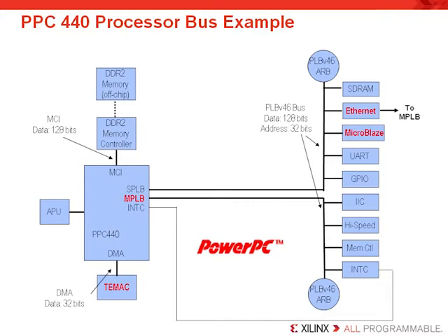You should also note that the MCI port gives 128-bit access to an off-chip memory, and that the 4 DMA ports give 32-bit access to a local link. The DMA is most commonly used to connect to the embedded TEMACs inside of the FPGA that may be dedicated in that FPGA. And those are dedicated, of course, in the Virtex-5 and the Virtex-4 FPGAs.